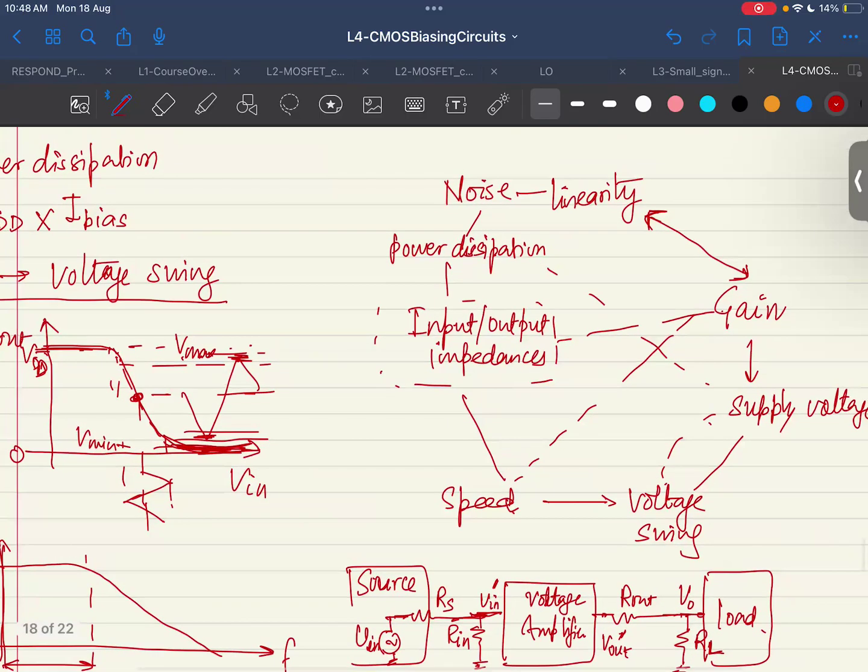Yeah, noise. So noise is something which we will also talk about, and we have briefly talked about in the case of a differential amplifier. We talked about that when we use a differential stage, for example, like in an op amp, this can really help us minimize the noise, or the noise cancellation. So noise is a reality in all the analog circuits, and this would always be there, and we'll briefly talk about noise in the later part of the course.